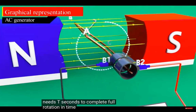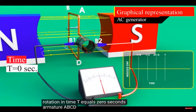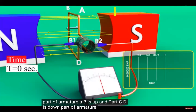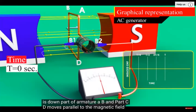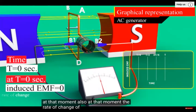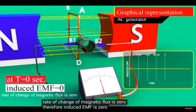rotation. In time, t equals 0 seconds armature ABCD is in a vertical position. Part of armature AB is up and part CD is down. Part of armature AB and part CD moves parallel to the magnetic field at that moment. Also at that moment, the rate of change of magnetic flux is 0, therefore, induced EMF is 0.